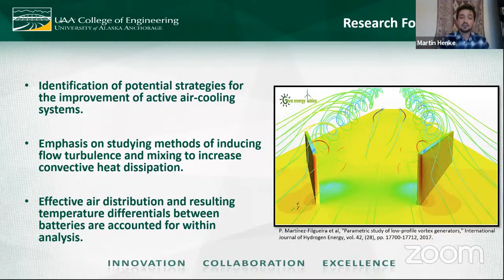And in addition, there's also the phenomenon of spot cooling, where certain batteries have localized cool spots or gradients on the body. And this can also damage a battery. So there's a reason that active air cooling has been avoided, because it requires proper design and implementation. Otherwise, it can harm batteries. And really, I need to account for that in my own research.